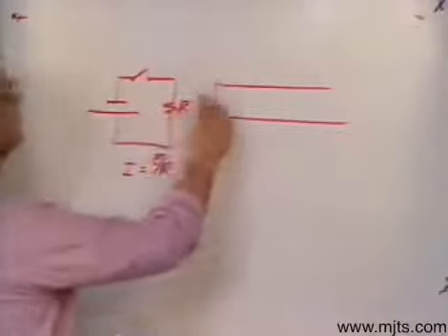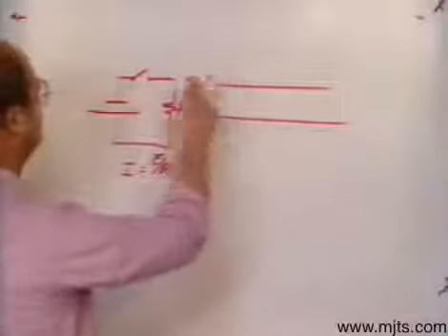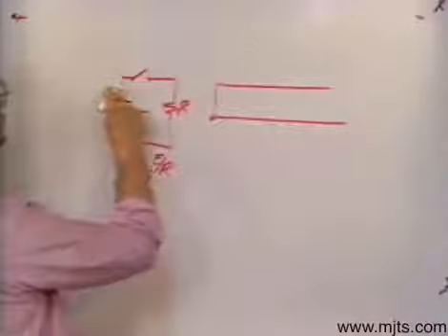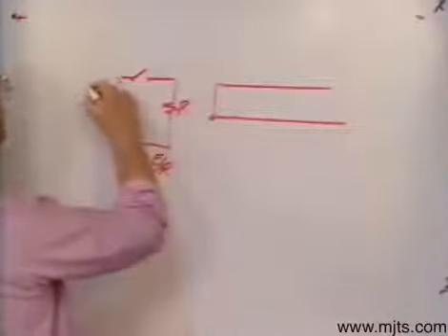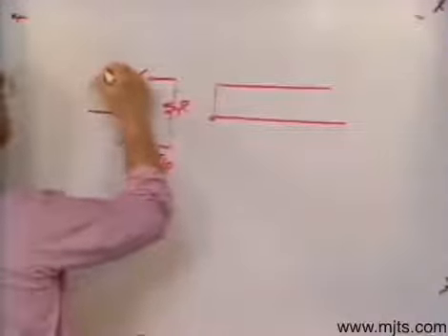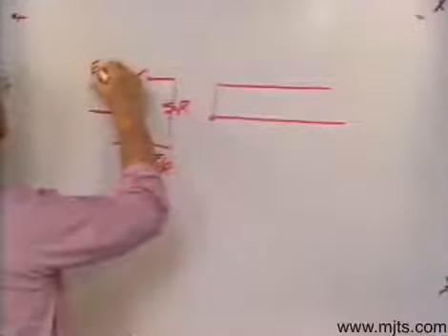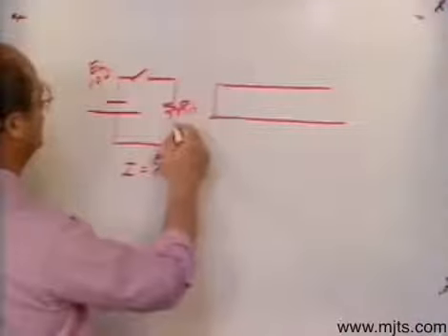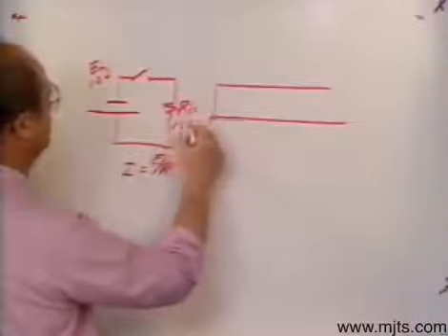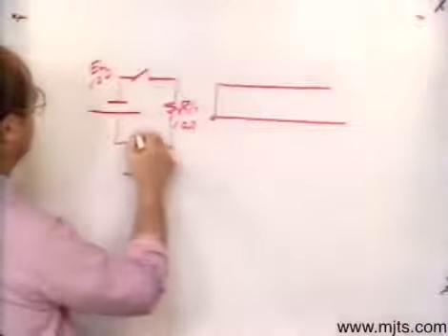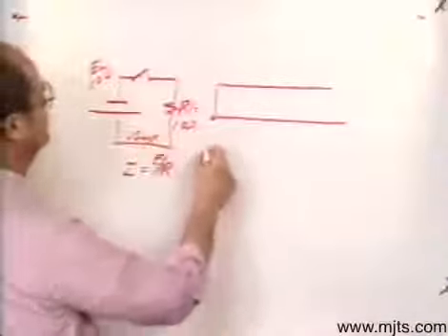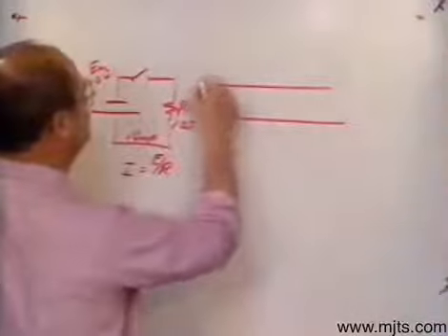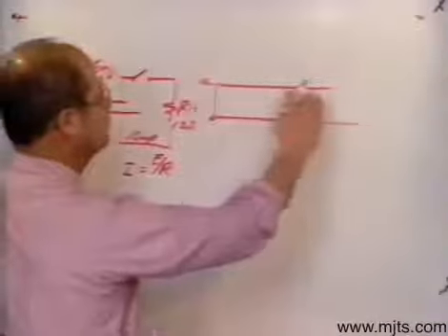The value of current would be dependent on the voltage and the resistance. If I had 100 volts applied to that circuit, and resistor 1 was, say, 10 ohms, I would have 10 amps flowing through that circuit. In other words, it'll instantaneously jump up to that 10 amp value.